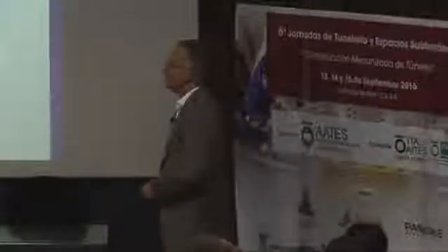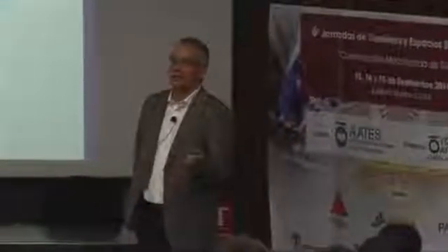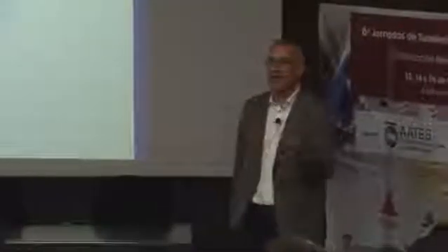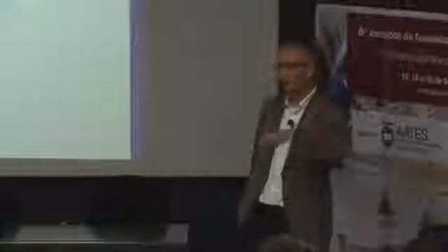We can have as well face collapses where you just can't operate anymore, out of obstacles inside, too much material for the cutter head to turn, any reason, you don't know why, and you have to enter into this excavation chamber.